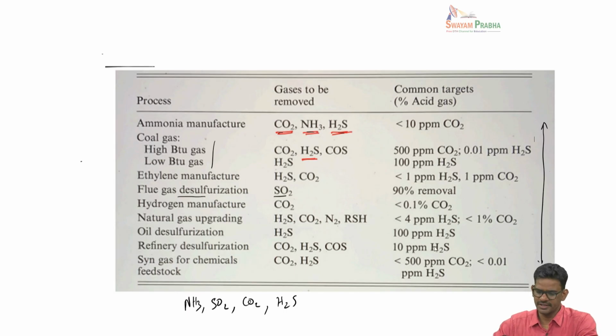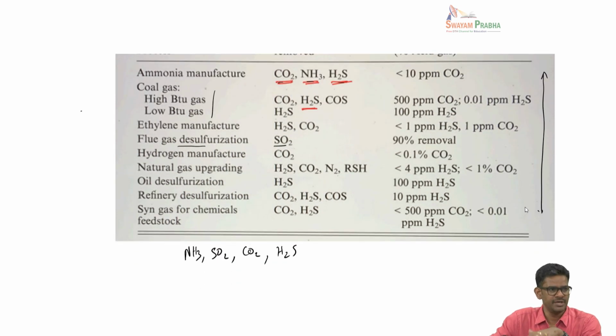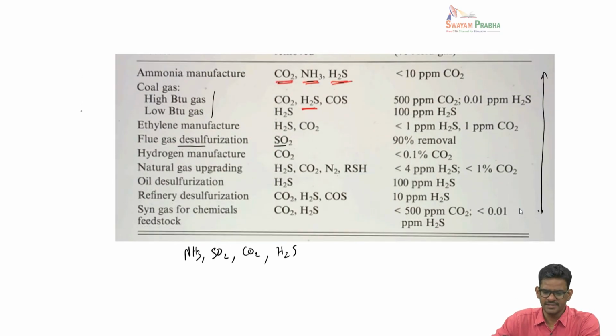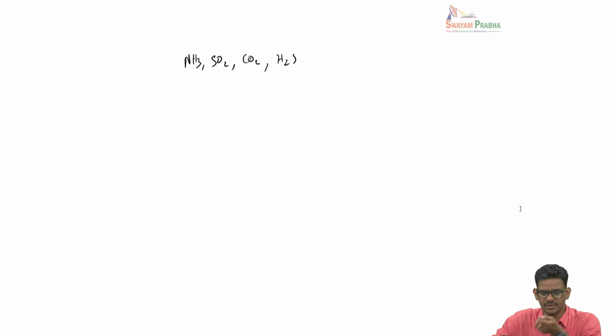So this is the context we are looking at: how to separate these harmful gases from the effluent is the problem of absorption. This will be a solute in a background gas. It can be air, or some other inert gas from which we have to remove this set of gases. As I said, it's a gas liquid operation. We want to transfer the solute into a liquid.